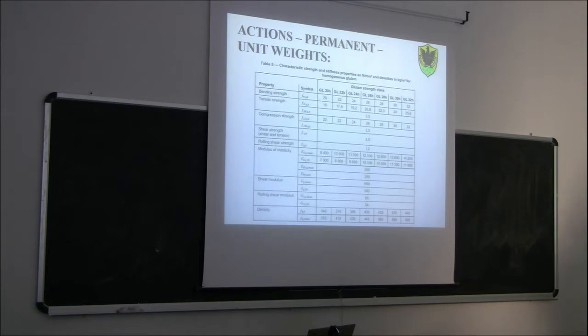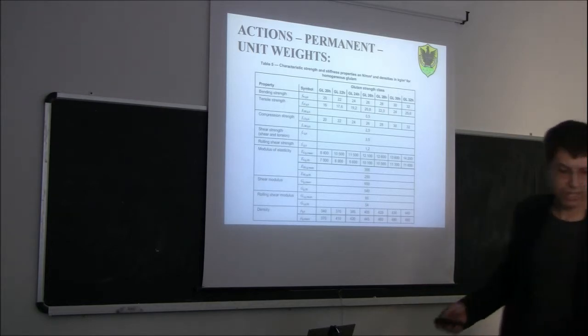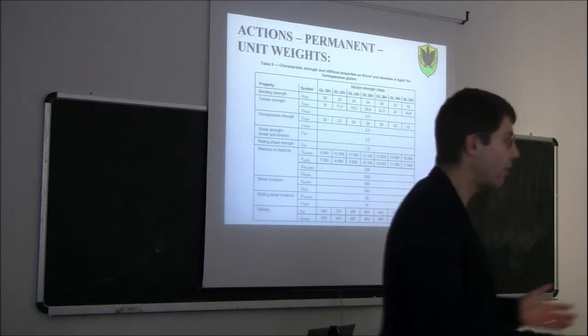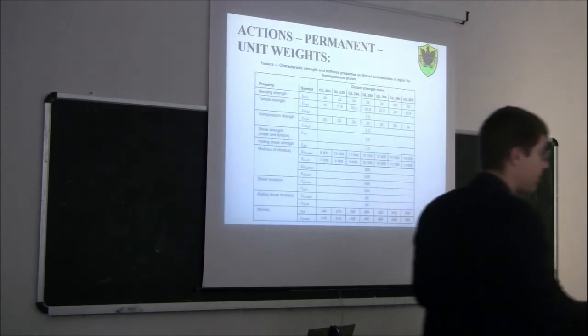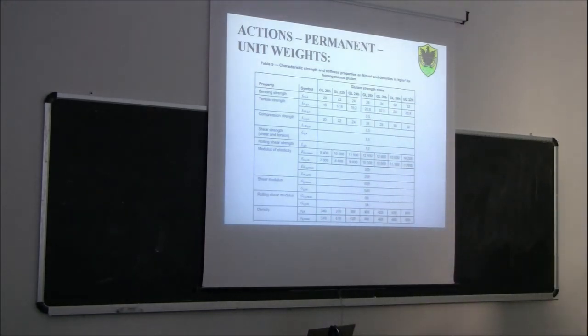Combined means that in the homogeneous section, we use boards all of the same strength, so all the cross sections are made from boards of the same strength. Instead, in a combined version of the beam, we put the best strength boards outside and the worst ones inside. Okay? That's the difference.